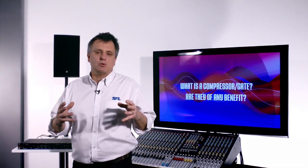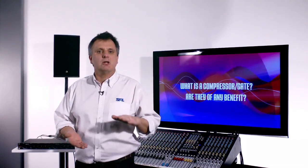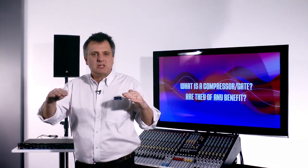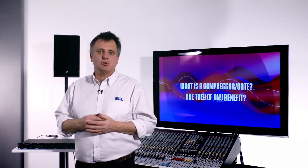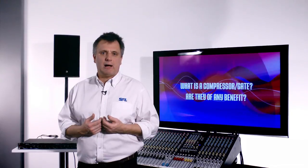The headroom resources that we have inside our amplifiers and our speakers are not infinite, they are finite. And if we take a signal and allow it to hit the top of that, we get limiting, we get clipping, and we get distortion. A compressor can help us keep everything within these limits. In modern mixing, it's likely that many of the channels will have compression inserted so that all channels have got this level of control. So how do we connect a compressor to our signal path?